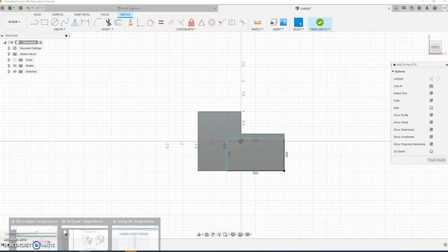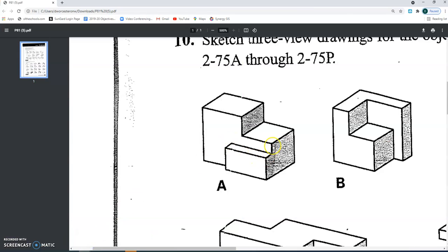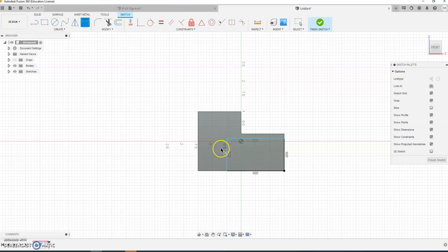When we look at our drawing here, we can see it's shorter than this other portion. We're keeping everything on a 1/4 inch increment, so we're going to make this a 1/4 inch shorter. We can see it sticks past this midpoint a little bit, so again, 1/4 inch increment, we're just going to make it a 1/4 inch longer. So we're going to come back here, dimension from here to here. If you don't remember, the other one was 1.5, so we're going to make this 1.75. From here to here. Again, if you don't remember, this is 1 1/4, so we're just going to make this a 1/4 inch shorter and make it 1. So there's that looking good.